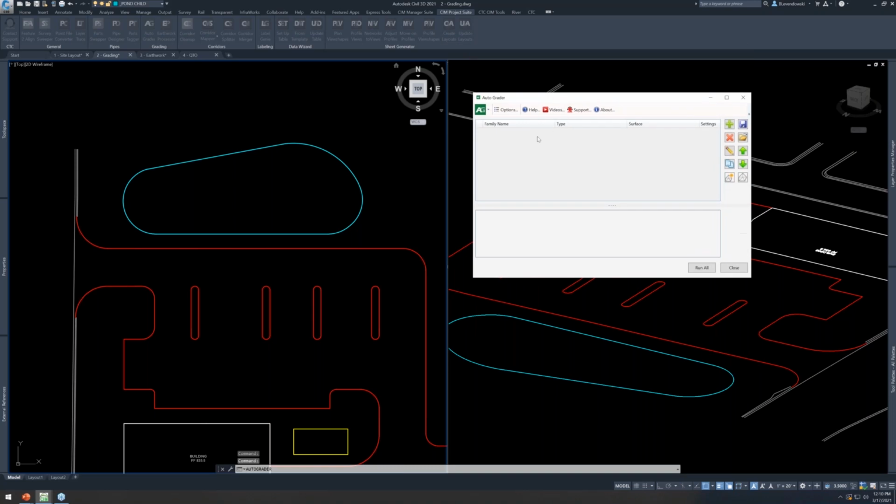Now this is a different drawing. So that curve family I created in the site layout drawing, that doesn't show up here. So these grading families save per drawing. And by the way, what we create in the drawing here, they're just standard feature lines. Okay, we're not creating any kind of CTC AutoGrader object. So anyone that you might share this drawing with, if they happen to not have these tools, the only drawback for them is that it's slower to work in that drawing because they don't have those tools, but they'll still be able to work with all those feature lines.